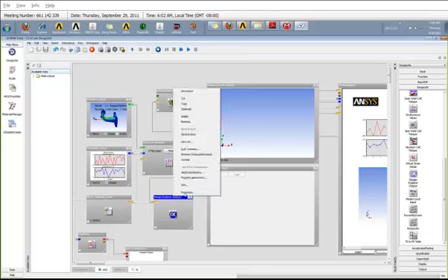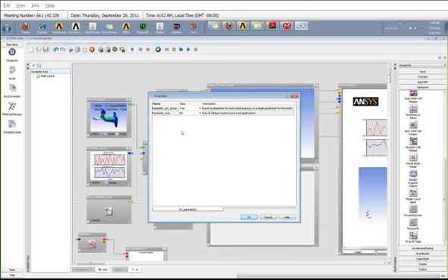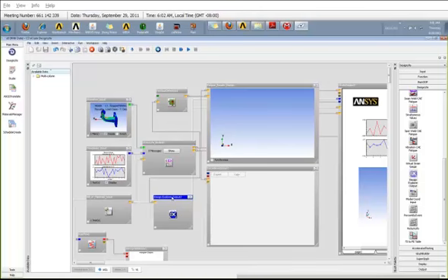Let's do a right click again, go to the properties and see what properties it has. So it has the option, either you want to parameterize your life, damage, safety factor, or scale factor. In this case, I'm going to parameterize my life. So I'm going to select life. And also, since it's just a single part, I don't want to have results for different materials. All I want is a single parameter for my model. So I'm just going to select false for my parameter per group. And the parameter type that I want to pass to the Design Explorer is going to be the life. And I'm going to give an OK.